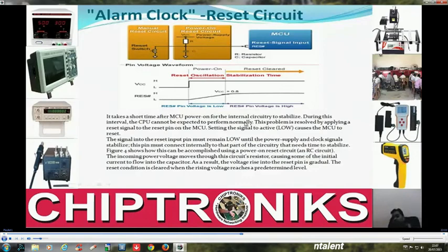When you give power to the microcontroller, or insert the adapter, and power reaches each component in a laptop motherboard, it requires some time for the internal circuitry of those devices to stabilize. During that interval, we cannot expect the CPU to perform any activity. So during that period we require the reset signal to be low, that is, active low.